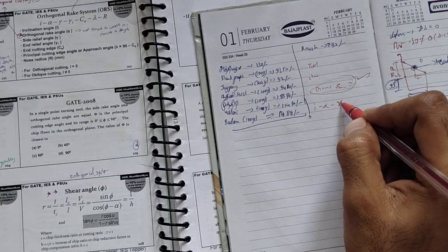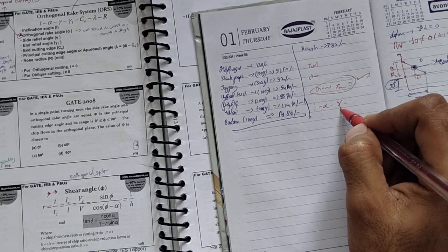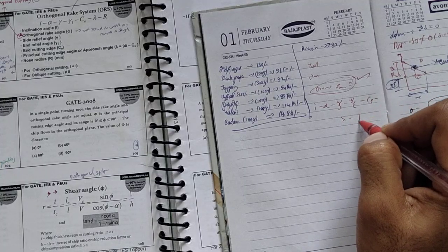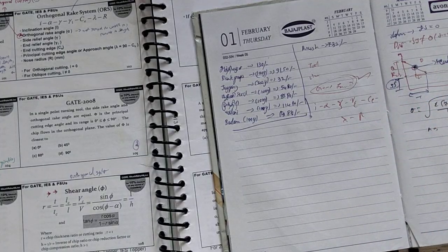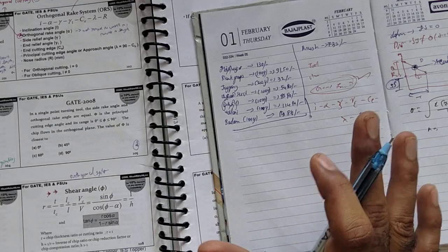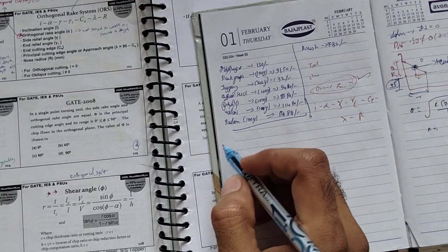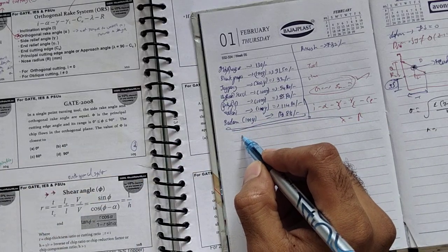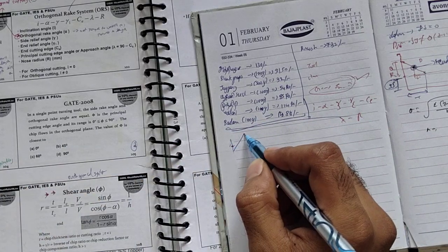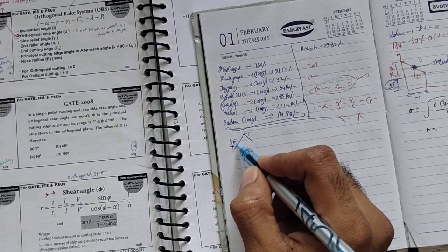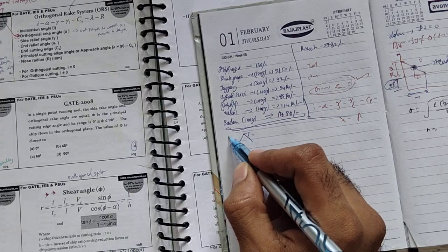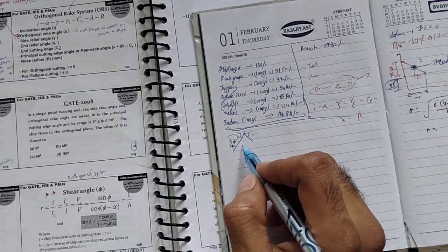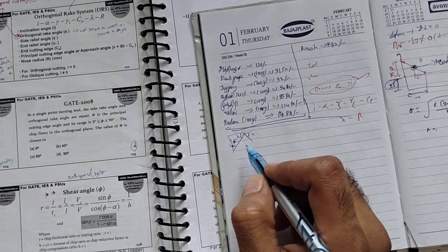This one has the end relief angle, side relief angle, side cutting edge angle, end cutting edge angle, principal angle, and nose radius, okay? I think you can understand, just a simple thing, okay? Whenever lambda is 90, it means the principal cutting edge is 90. So like this, this is the side cutting edge, this is the end cutting edge angle, and this is the side cutting edge angle, okay? So this is lambda, just a simple thing, okay? While you make a summation of this, it will come according to the angle, okay?